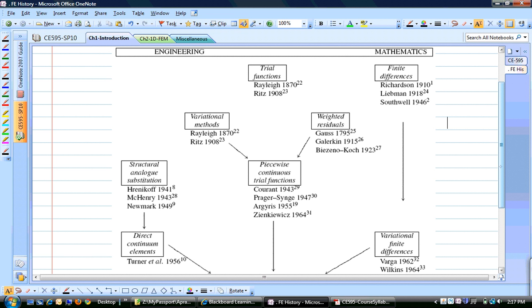To solve that equation, you can either use the method of weighted residuals, that is your principle of virtual work. So weighted residuals is nothing but your principle of virtual work. Or you can take an energy approach. In both cases, you will end up with the same mathematical model, which you then discretize using finite elements, and then you solve your discretized mathematical model.